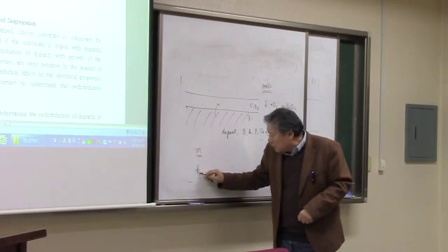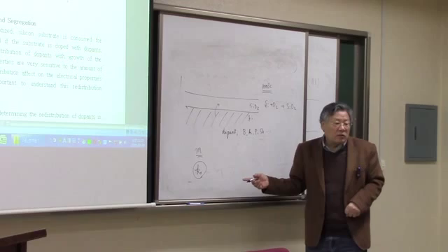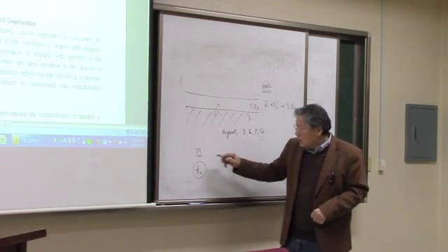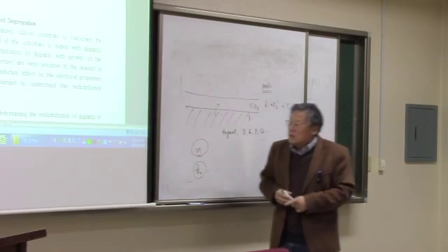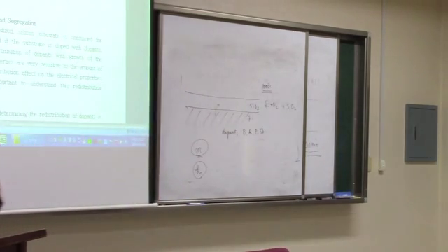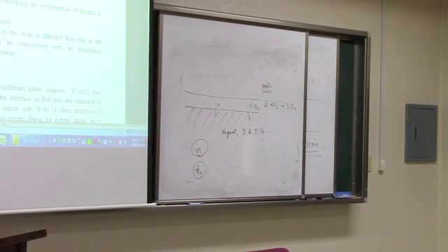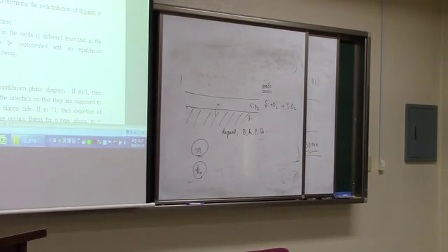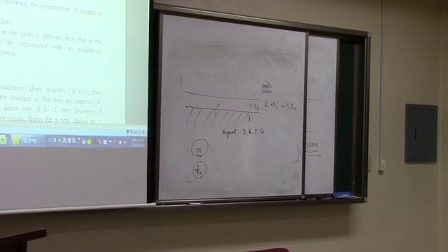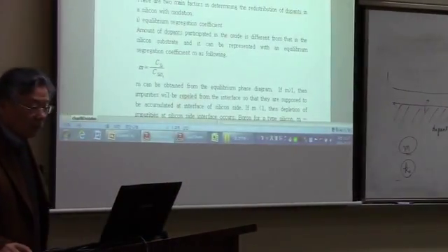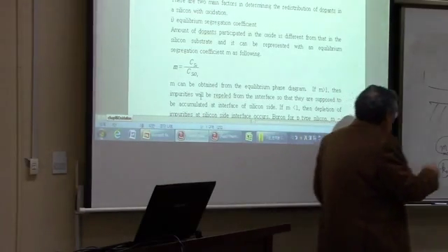We have the equilibrium segregation coefficient, like the K naught in a Czochralski crystal growth. Here we have M, which is going to be called the equilibrium segregation coefficient. That is the dopant concentration in the silicon over the dopant concentration in the silicon oxide, and this silicon oxide is going to be grown on top of this silicon. Now, if the value M is less than 1,